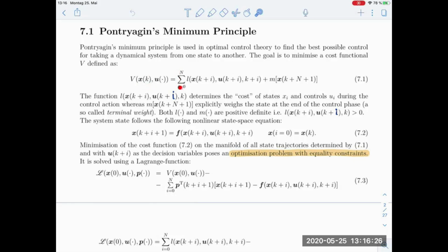We look at several time levels, and here you see how we formulate these costs, still in a very general way. We have a counting index i that we sum up over i from 0 to some horizon length N, capital N here. So that's the number of samples plus 1 that we consider. And over these time instances, we sum up a function l, lowercase l, which is a function of some states x, of inputs, and maybe of time itself. So this l here essentially formulates a cost defined on the current states and on the current inputs that drive the system. And it could be time dependent itself as well. But for the time being, we will not specify more closely what l actually looks like.